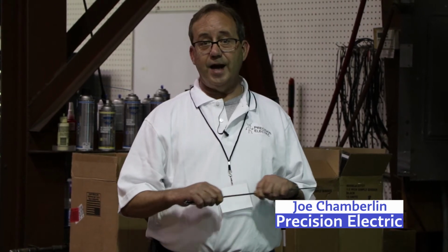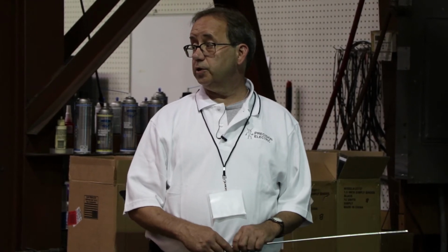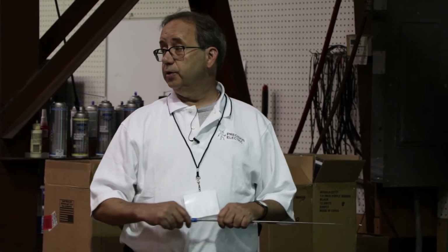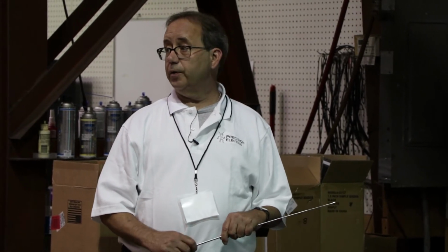Because if it's not, then it will create sparking at the comm, wear, premature brush failure, and that could be a reason for sparking at the comm too, is if you have an interpole that's bad or one that's grounded or something like that.